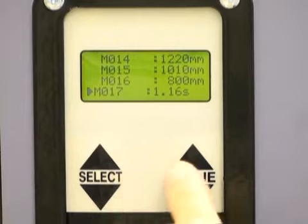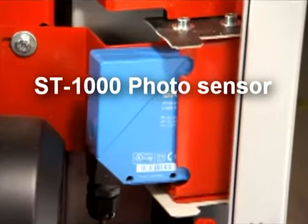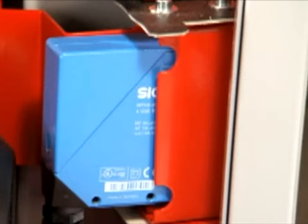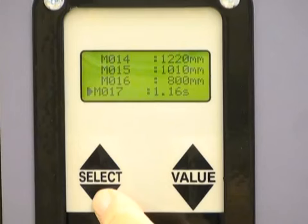M017 I Delay defines the amount of time the carriage will continue to travel once the top of the pallet is seen by the photo sensor. Changes to this value change the crossover X position, also the position of the looping. In most every application, changing the factory setting of 1.16 is not required.